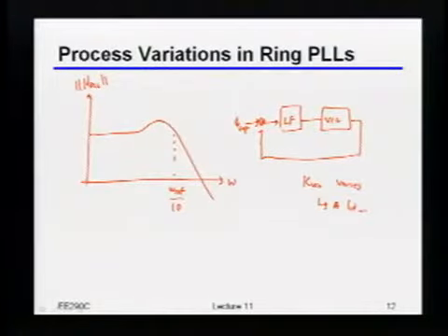Yeah, so if I increase the KVCO, that's like saying I've increased the forward gain here, right? So from an open loop standpoint, I'm pushing out the crossover. And if I've got some third order pole or just my sampling frequency or whatever sitting there creating some large phase delay, then if I increase that KVCO, guess what? This thing will just go off to infinity, and you'll be unhappy and nothing will really work, right?